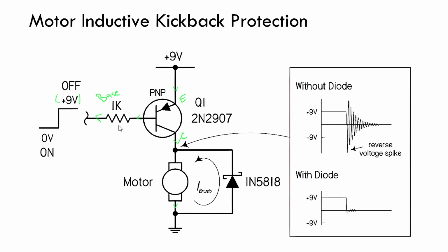So why do we talk about kickback protection? When someone suddenly closes this circuit, the motor opposes the change in current, because there is an inductor coil inside it. As you already know, a motor has a coil. Previously the motor was working fine with the supply positive and negative. When someone suddenly switched it off, it opposes the change in current, and a reverse polarity is created here.